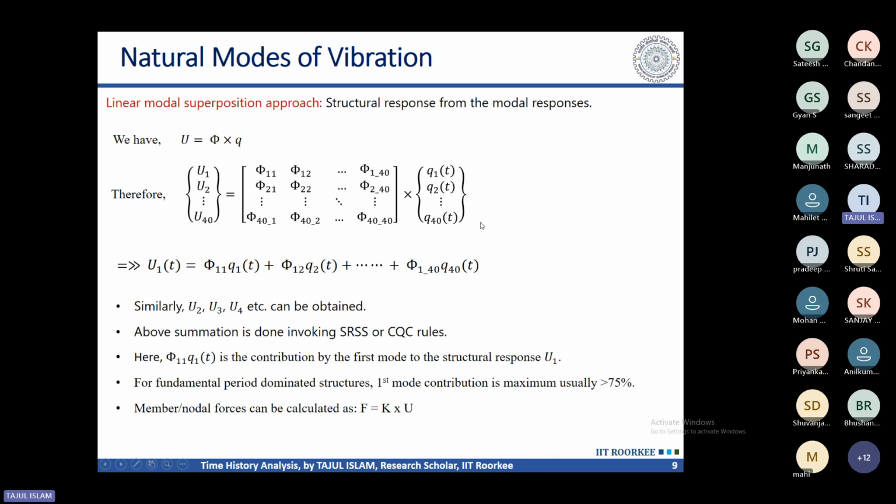Now, in this extraction, what I have considered is a 40-story building, and only lateral modes, meaning lateral deformation, and other deformations I have locked. Means in one node there is only one deformation which is in the lateral direction. So this way, for a 40-story building, I will have a total of 40 modes, so 40 story deformations.